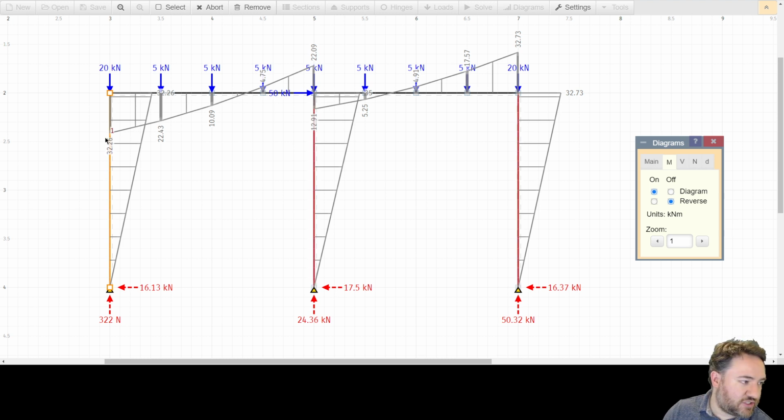Okay, so I have 32.07 at the end here. So that's my moment. You can see that the moment is not totally even between these two because we're doing an indeterminate structural analysis. I can see the moment in the column at the top here, 32.6. I can also pick up some in-between ones. Obviously this should be a straight line for this particular analysis, for the columns, certainly.